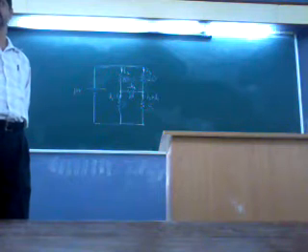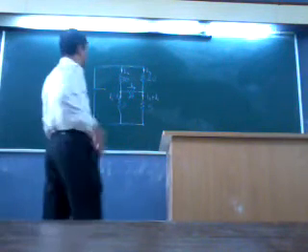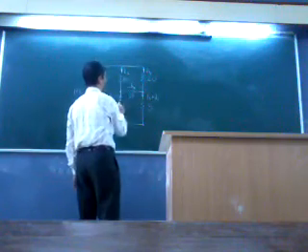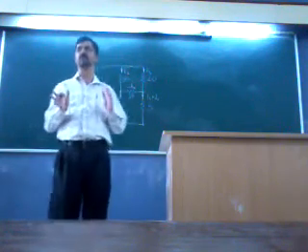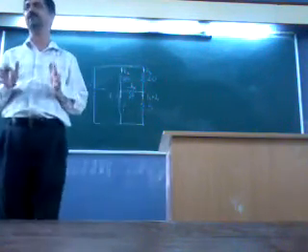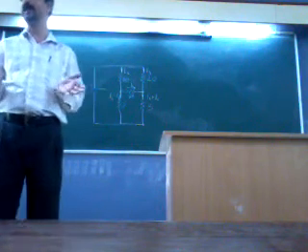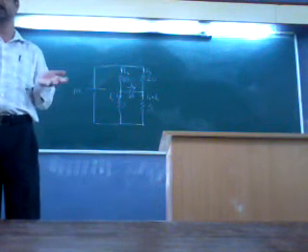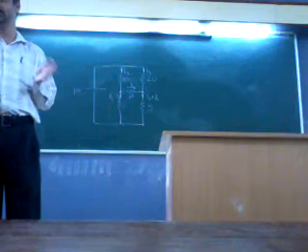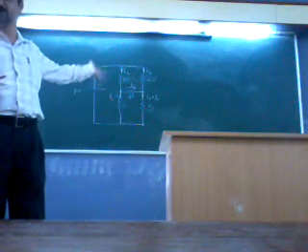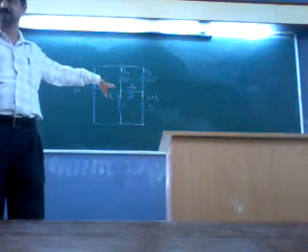Otherwise what will happen? Otherwise there are how many arms independent? 1, 2, 3, 4, 5. So you have to presume 5 currents, I1, I2, I3, I4, I5, and then apply Kirchhoff's node laws. Then you can reduce some equations. So that we do not do. We immediately use the laws to define the currents. Is it clear?